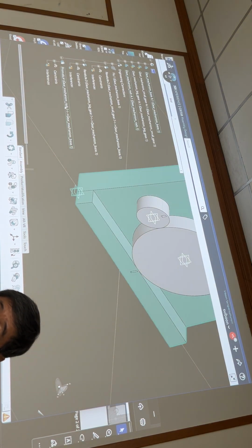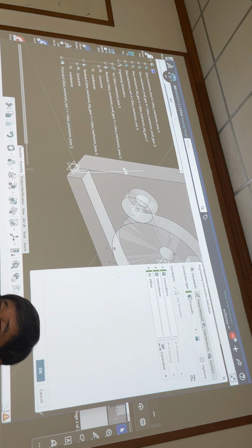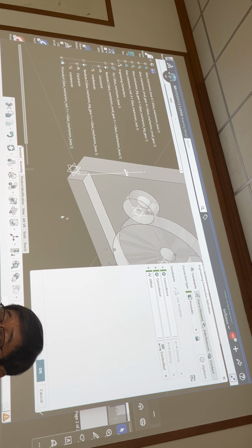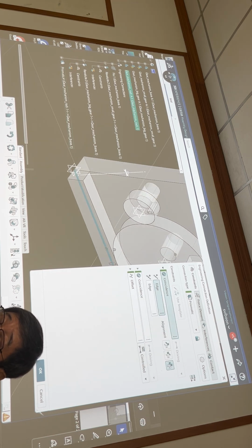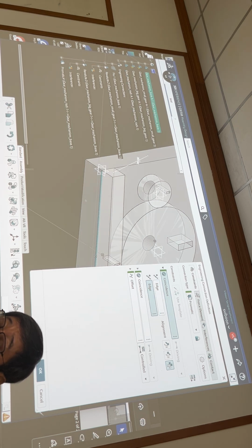The other one as well. I have a prismatic joint here. I also choose the prismatic joint from the template. We have coincidence between what? The axis of this one and the axis of this one. You can use alternate selection if they overlap.